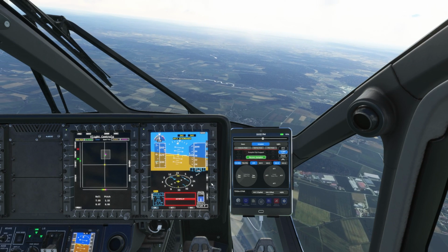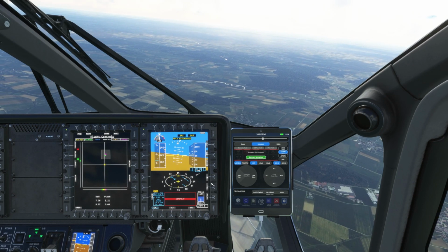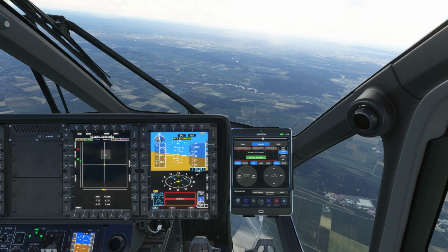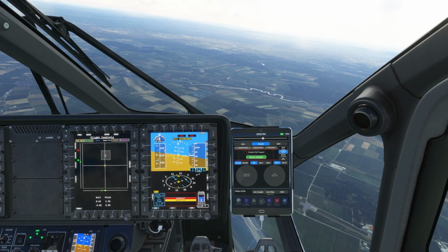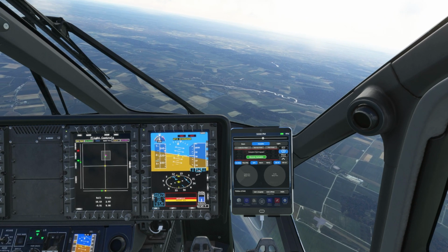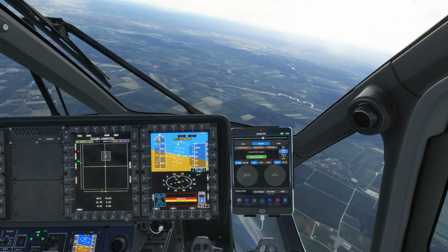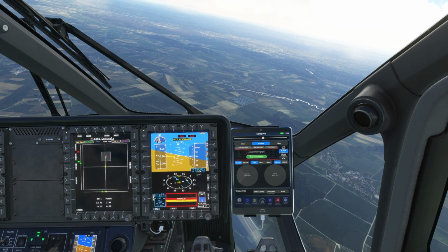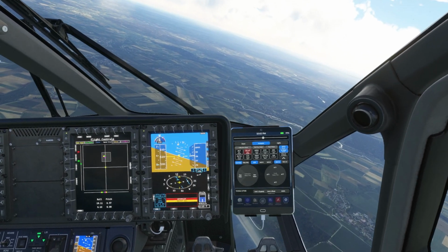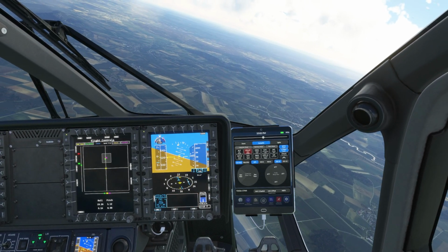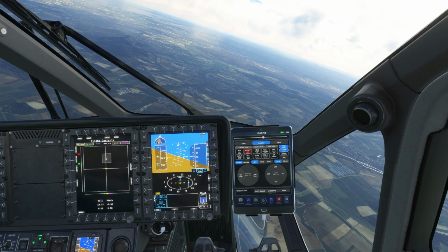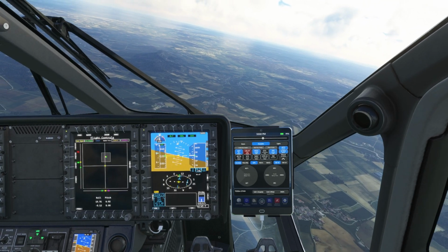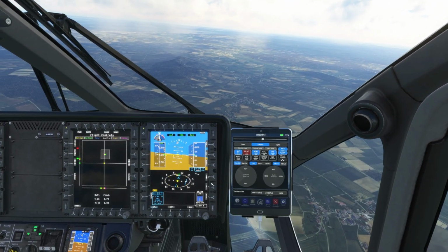Part of the emergency procedures, if you needed to, you could press AP cut. AFCS is disengaged, the backup system is actually taking over. So you don't have the full upper modes anymore. Pressing that AP cut a second time actually disables everything. So there is no AFCS, no SAS system. Autopilot 1 and 2 and backup are all disengaged at that point. I'm going to turn those back on, and I'm actually going to engage the upper modes again to get us back on course.